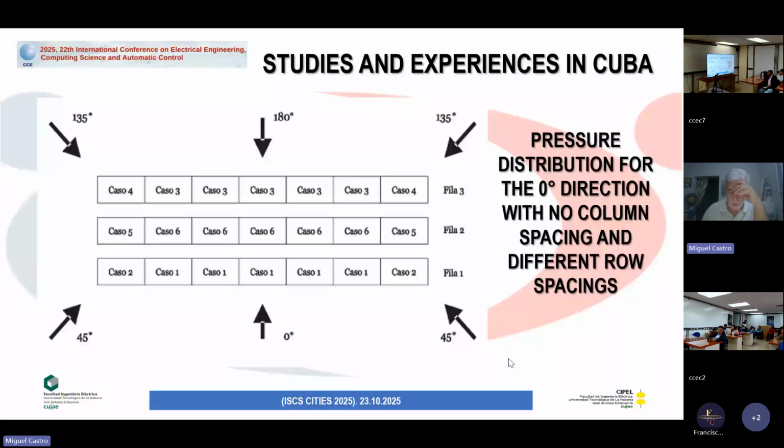These studies show that for the separation between rows, considering 2 and 3 meters of separation, the highest pressure values were obtained for the first row, which offers protection to the second and third rows, independently of the separation analyzed. Also, the highest values were obtained at the edge of the first row. However, if this separation is only 1 meter, the edge of the panel of the second row, being so close, is submerged in the separation wake in the boundary layer of the first row.